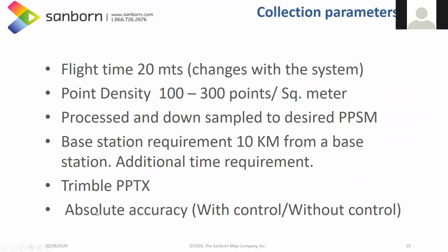And finally, the most important thing we need to think about is the absolute accuracy. What sort of absolute accuracy we are going to get with ground control, without ground control, and whether it is in line with the client expectation, that needs to be determined.